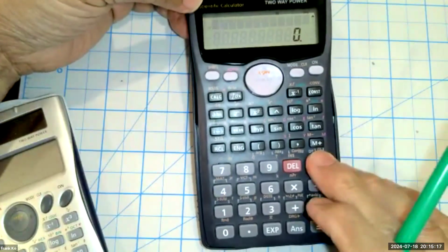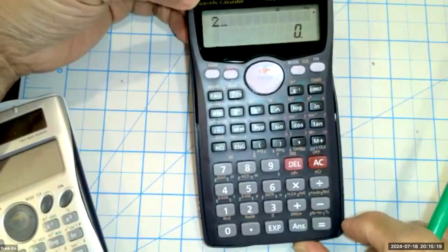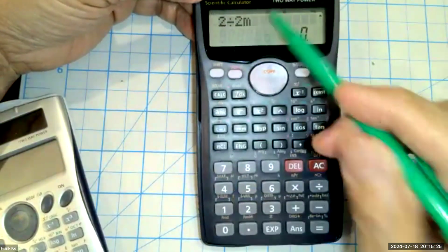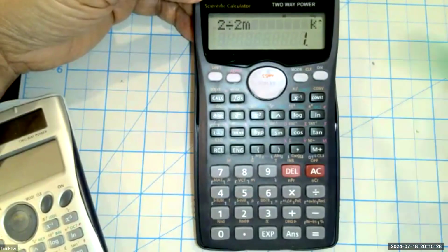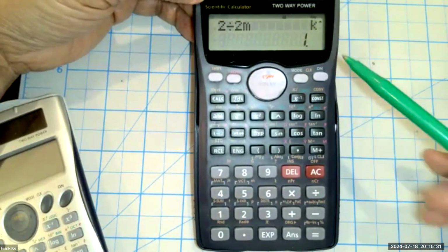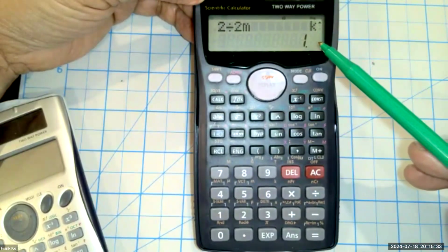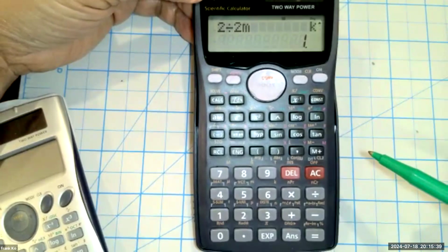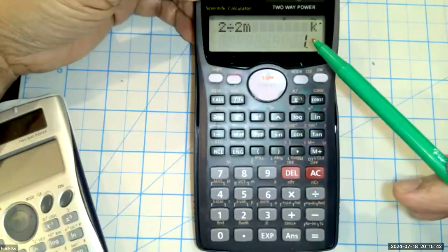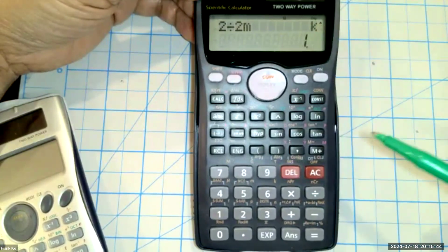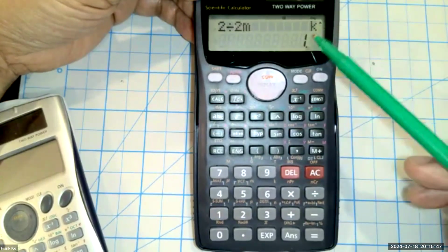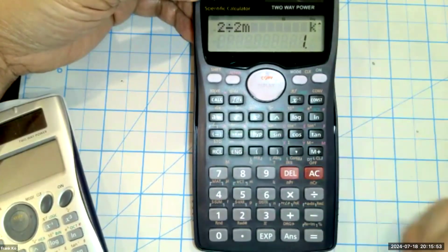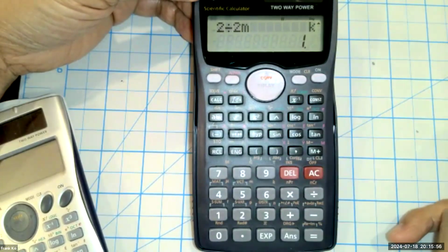Okay. So next, we're going to do the calculation for R2. R2 is going to be 2 volts divided by 2 milliamps. So 2, shift, there's my milli. And according to my prefix, I get a resistance of 1 kilo ohm. It wasn't previously 1 kilo ohm, but now under these conditions, it must be 1 kilo ohm. So write down R2's value equals 1 kilo ohm. Hopefully as you've gone through these steps, you calculate the same.